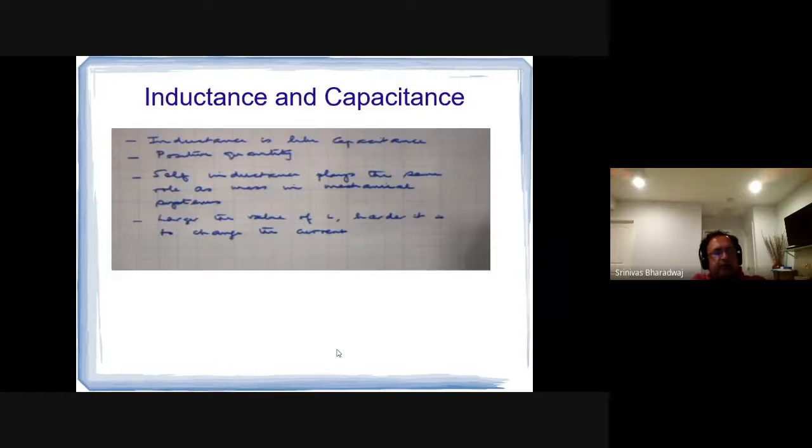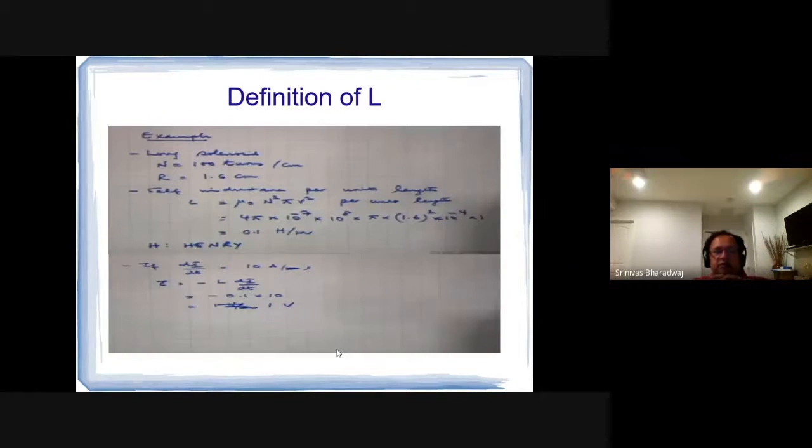Now that formula, I equals C dV by dt. This formula is V equals L di by dt. So these two are kind of alternatives of each other. In one case, you integrate for the current. In the other case you differentiate for the current. So in the inductor, you differentiate for the current. In the capacitor, you integrate for the current. Therefore, these are used in circuits together. And very often what they do is they produce oscillatory circuits. And this is where we are headed now.